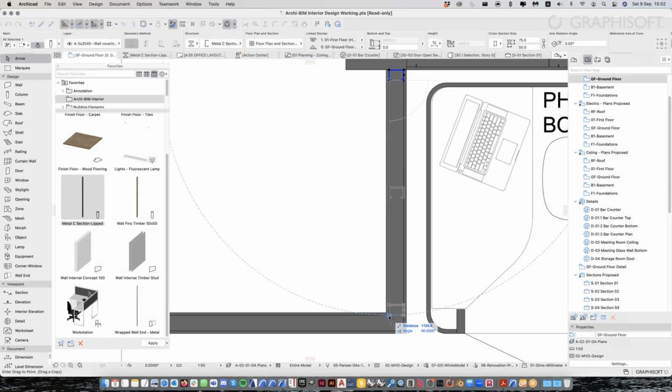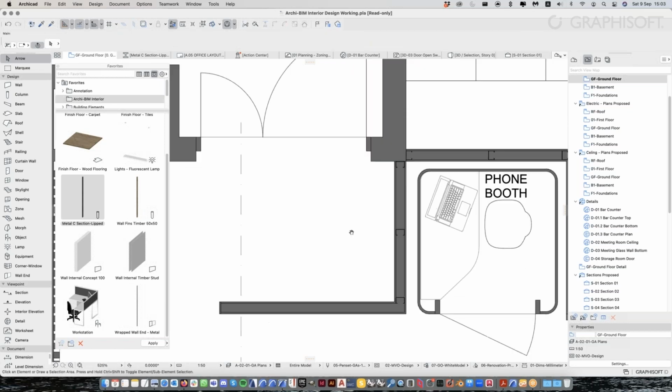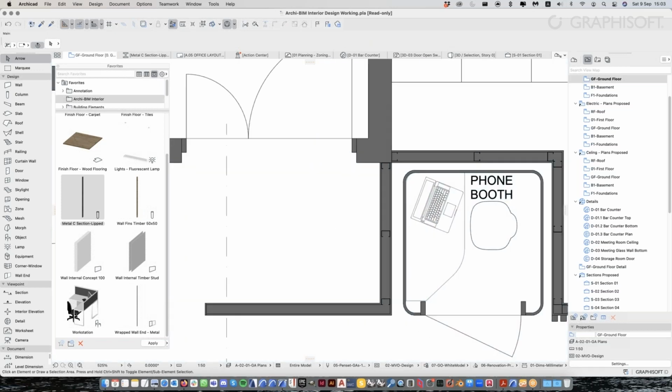And you see that 2 more copies are made, and the last piece, that point, will be placed here. So I just need to click, and it will help me put 2 more copies. So this is how you can use multiply to quickly do an array. And the good thing is you can preview it. So I think that's very handy.